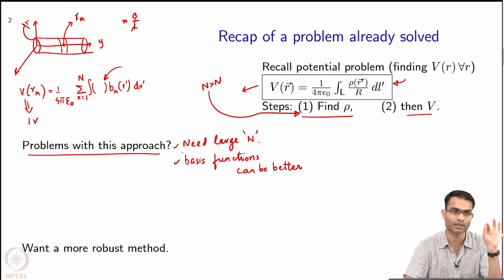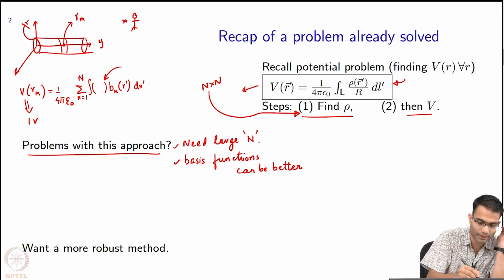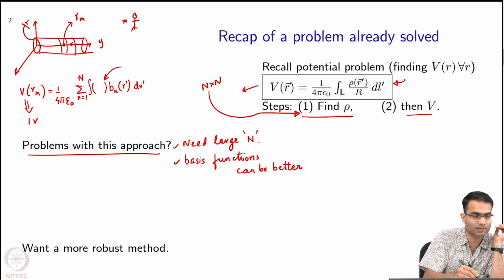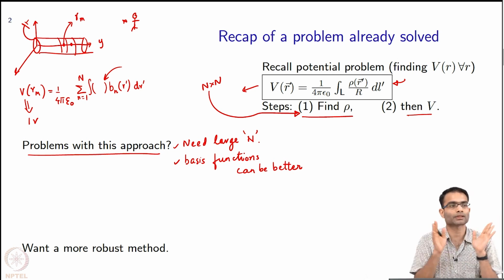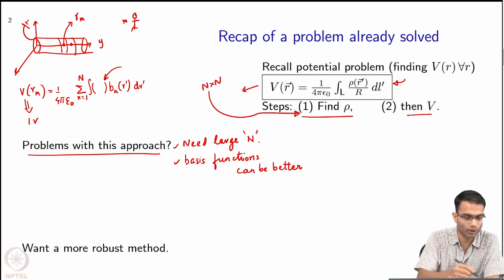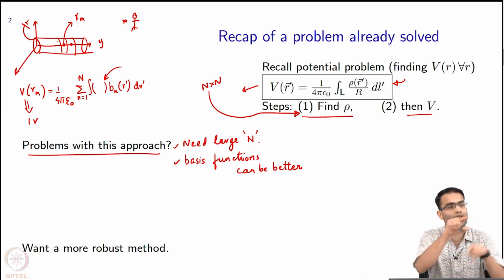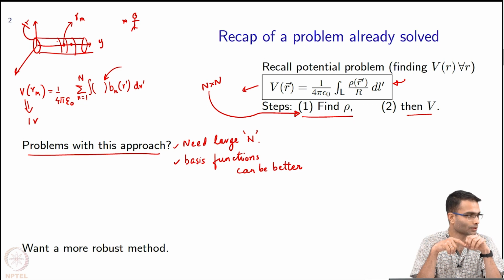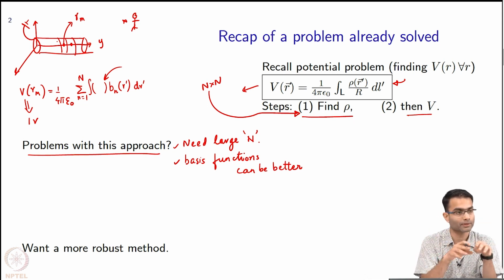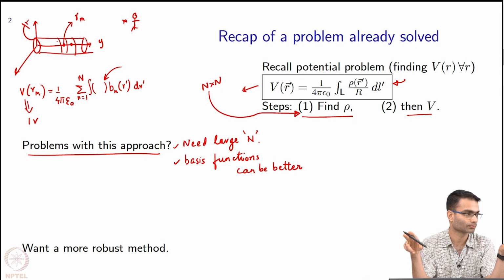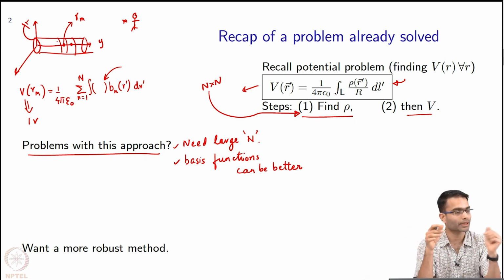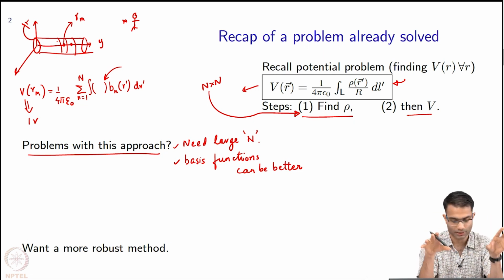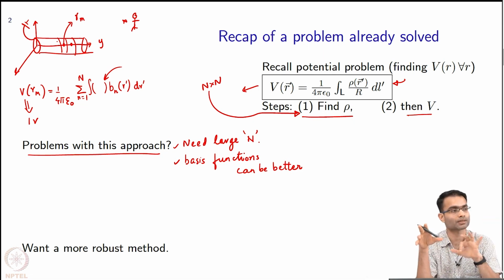We are enforcing the left hand side at Rm, then the next, so we have one segment over here, we have one more segment over here. So first equation will take this point, second equation will take this point, and so on. But we are doing nothing, we are just hoping that the solution turns out to be smooth and well behaved and all of that. But we are not doing anything to ensure that the solution is continuously 1 volt everywhere, right? 1 volt at the cell, right? Yeah. 1 volt, no, the voltage that is given is at every point on the wire. But we are increasing n. As we increase n, we are approaching that. So my question is that keeping n fixed, choosing good basis functions, still is there something better that you could do?